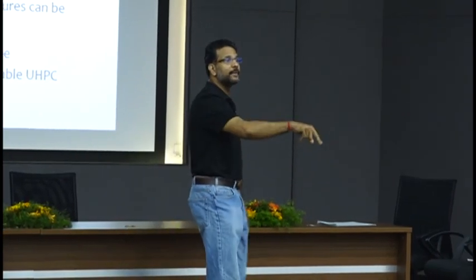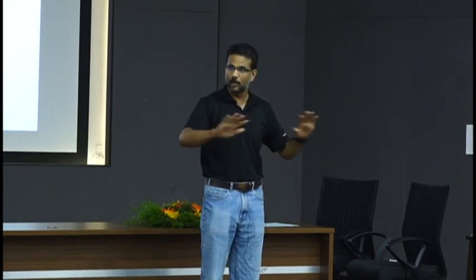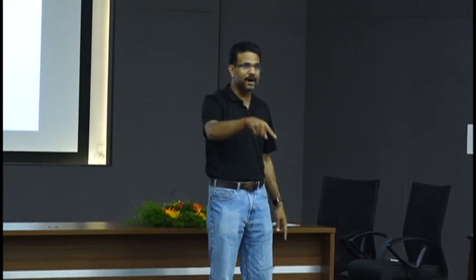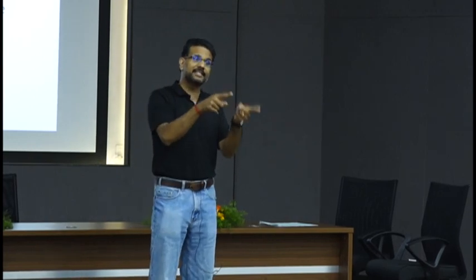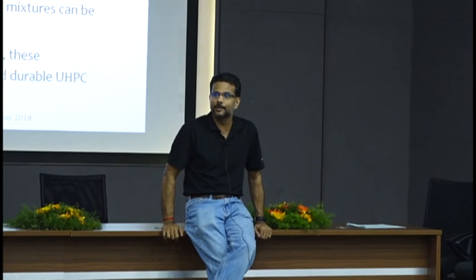Now, you throw some sodium hydroxide in the system like you do for geopolymer activation. Your calcium hydroxide will say thank you very much, it will sit there, and fly ash also will sit there. Fly ash and calcium hydroxide will not even show that they know each other. They will not do anything because sodium is now more powerful than calcium as a cation, and sodium will say, I'll do my job, you guys keep going. Right? And if you have a cement with a higher alkali content, that's exactly how it's going to happen. So if you have 1 or 1.2% sodium oxide in your cement and you're expecting your fly ash to do your conversion, you will not get the conversion that you need.